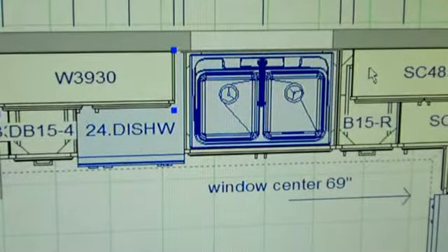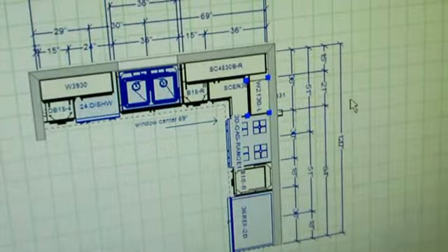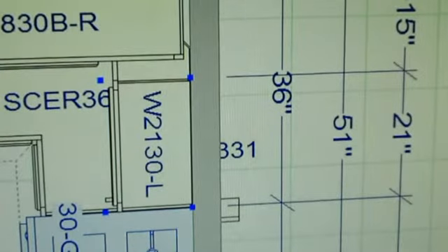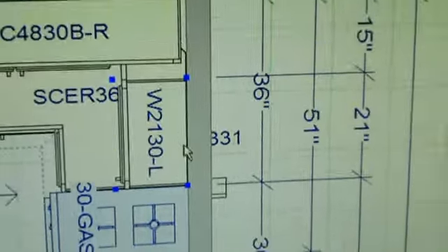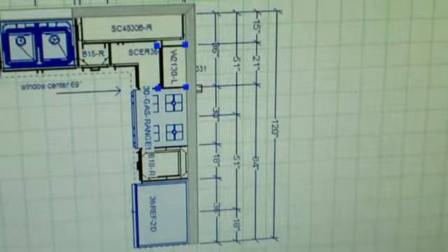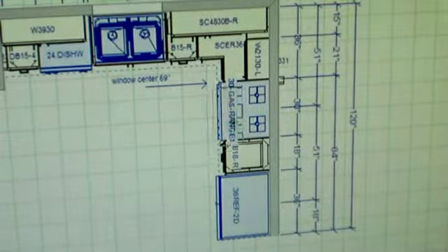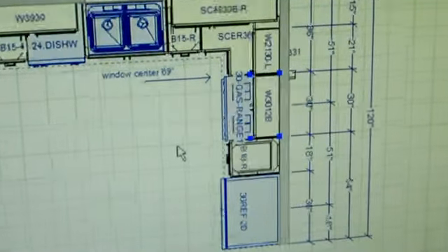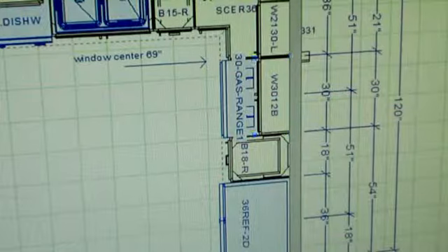So if you watch these dimensions, you'll notice that on the right, it was just a little farther off the window edge than it was to the left. I'll concentrate more on that in a minute. So off to the 36-inch edge of the Lazy Susan going next to our range, I put a 21-inch cabinet next to that wall blind corner. And remember, we always use a spacer next to a blind. So that actually occupies 24 inches of space. So the 12-inch depth of the wall cabinet, the 3-inch spacer, and the 21-inch wall, that's 36 inches.